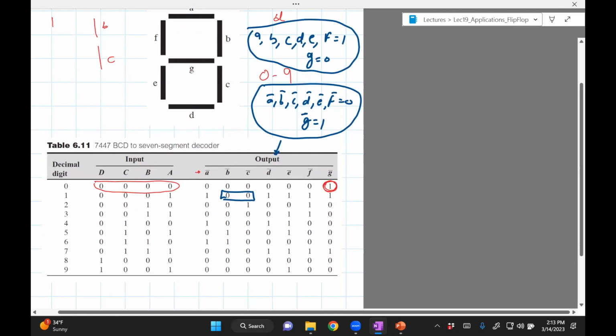In order to do this, you have seen this before. If you have a truth table like this, you can figure out the logic using the sum of products or product of sums rule. Then you can hook up the right number of logic gates to build it. Now the problem is that this is pretty complex, and building that logic circuit on a breadboard is going to take a lot of wiring.